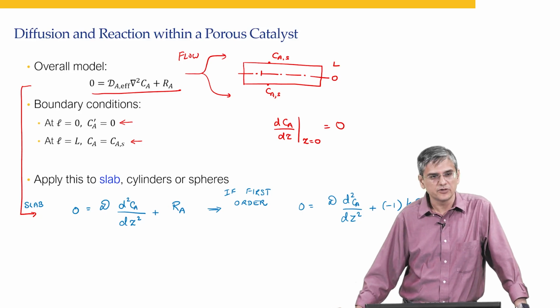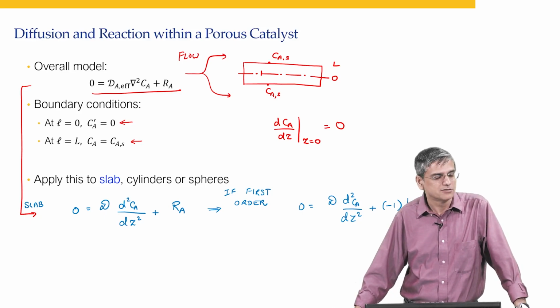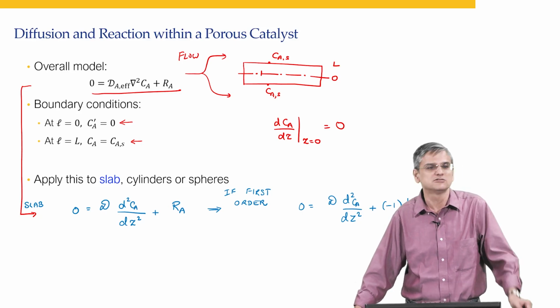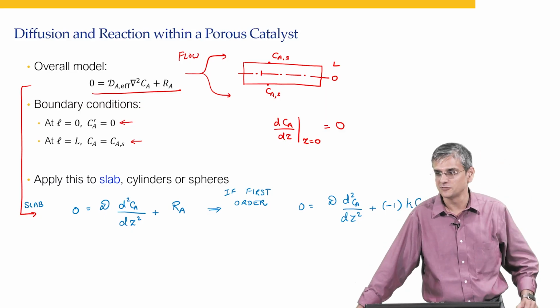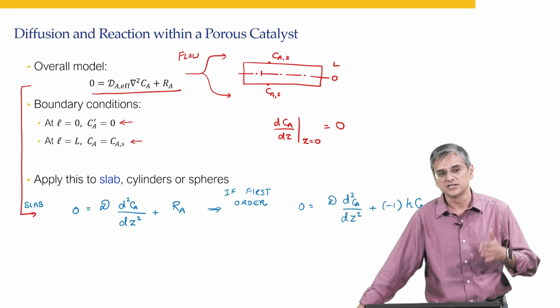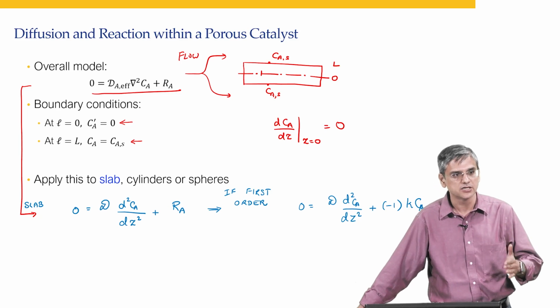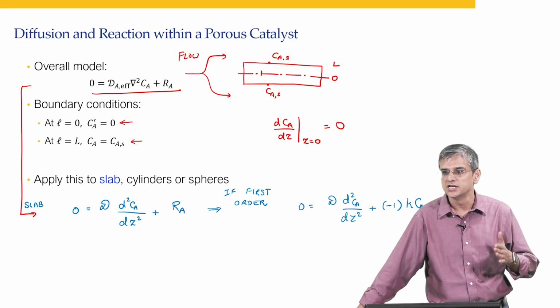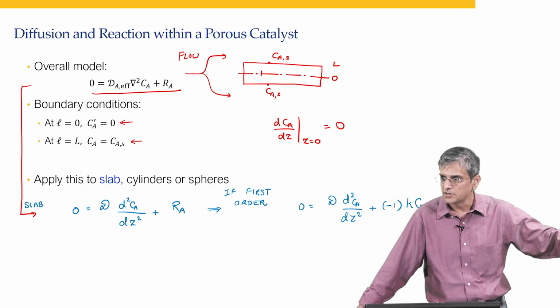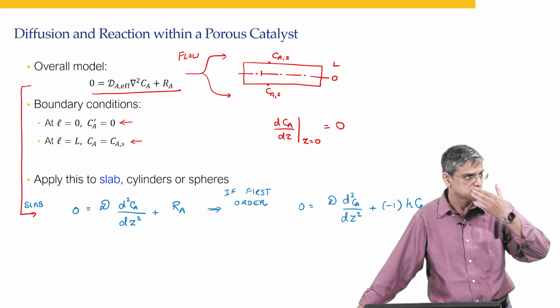I remember when I was younger, I would ask the question, why are we doing this non-dimensionalization? My answer would be, because it is always done like that. No, there is a reason why it is always done like that. The reason why we work with non-dimensional quantities is because you can analyze a particular system independent of the size of the system.